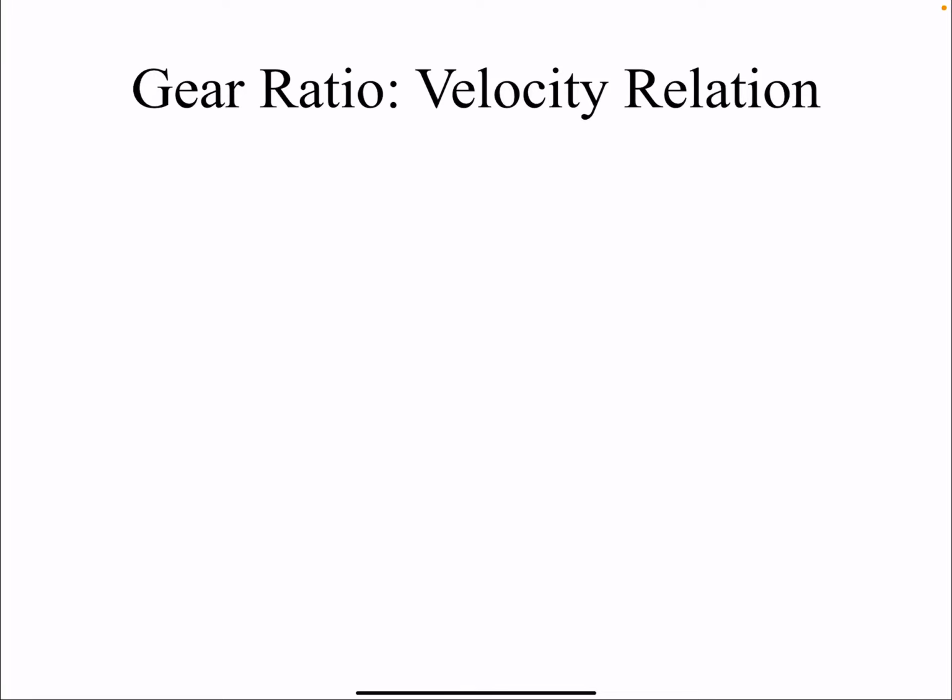Hello everyone, in this video I'm going to talk about gear ratio. So we use gearing to increase the torque, decrease the speed, or the other way around. As we previously talked, we know the power is T omega, and if two gears are in contact, usually we are increasing the torque and decreasing the speed, but there are some applications where you want higher speed as well.